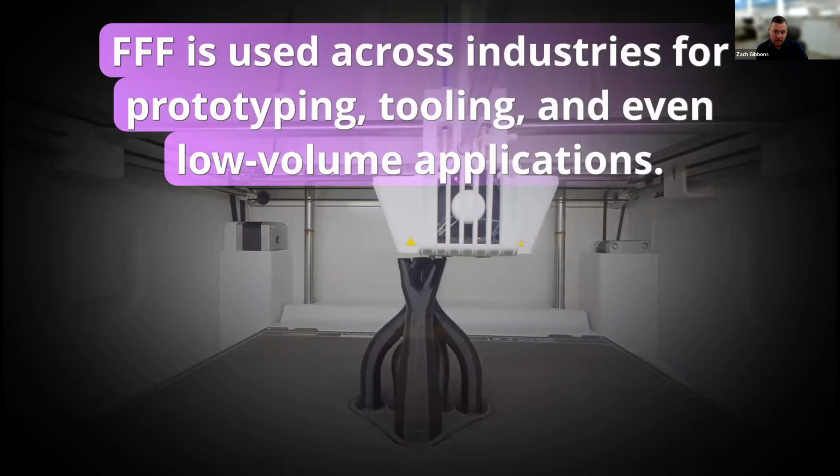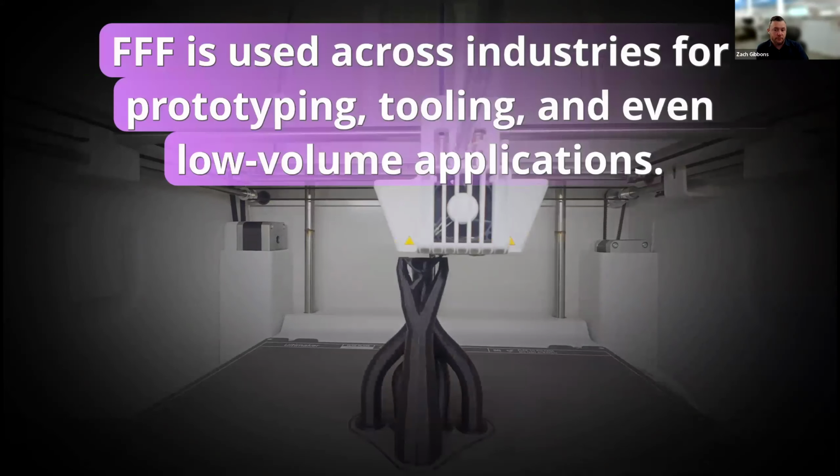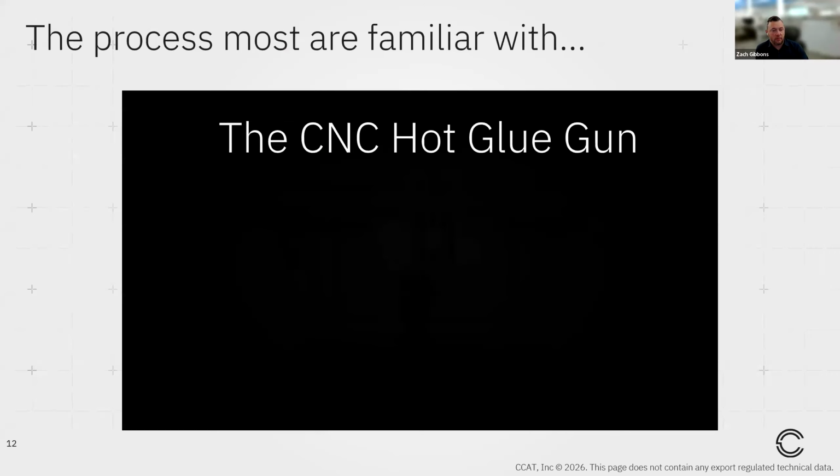So anisotropy, meaning we have different material properties in different directions. And that is true of almost any layer-based manufacturing process. When we make these parts, we're going to have differing material properties, and that just adds challenges for us as engineers, as designers. When we go to actually design a part to be additively manufactured, we need to be able to account for that anisotropy. So this is a process most folks are familiar with, aka desktop printing.